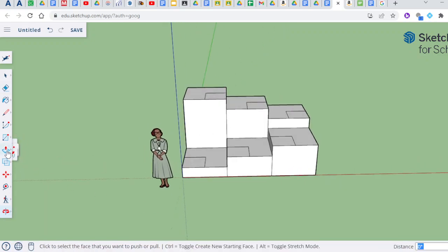So if you grab the push-pull tool, you click on this, right? You just start moving it down, and that's the distance down that it's moved. So just type in 6, hit the quote mark, which is shift and the key above the apostrophe, hit enter, and it moves it for you. Do the same thing here. Click on it, start moving it down, hit 6, shift, and the quotation mark, hit enter, and then just keep doing that until you're finished, and you'll finish.